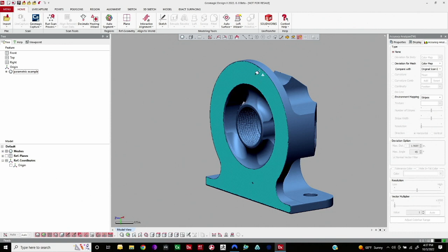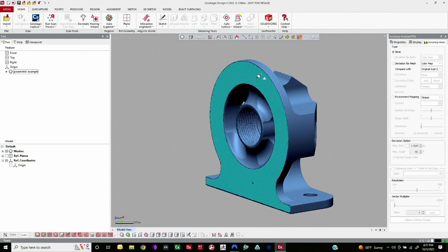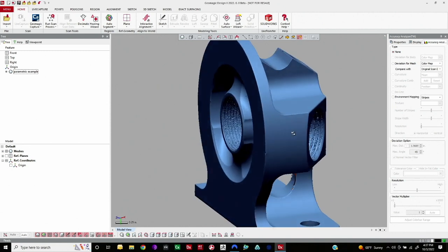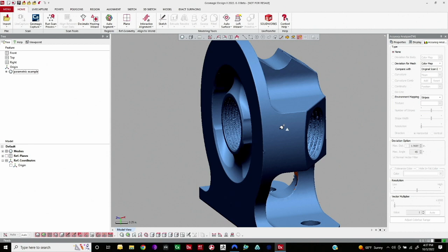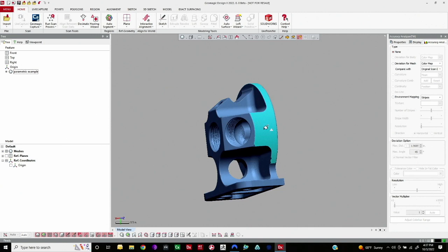So I clicked on this plane here with a single click and then drag my mouse up while holding the mouse button, and the selection tool becomes more tolerant of changes in normal direction. The same thing would work if I had clicked on this curved surface here. It's going to become more and more tolerant of surface curvature changes, and you see I very quickly and easily selected that cylindrical surface there as well.